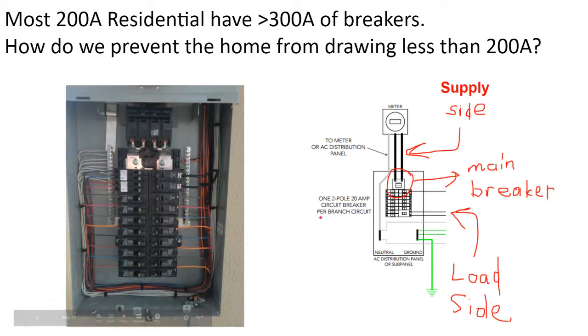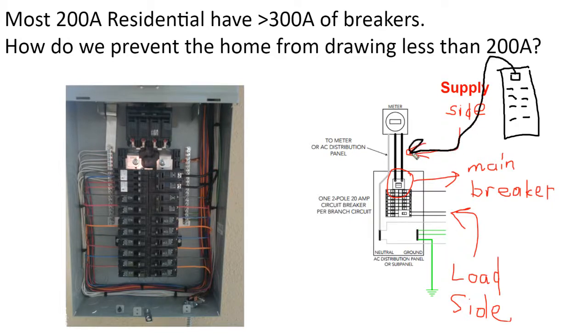So the takeaway is either the solar array will land between the utility meter and the main breaker as a supply side connection, such as for a larger solar array or for multiple solar arrays alongside battery inverters. For this reason, I recommend installing a 200 amp disconnect switch as well as a dedicated electric service panel, which will be adequate to prepare the site for future expansions, such as the ability to combine solar with batteries to run the home off-grid during a power outage.